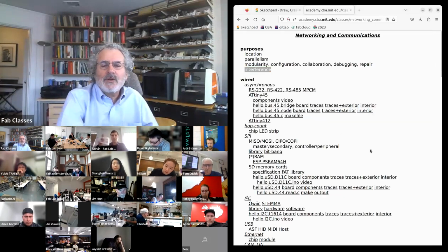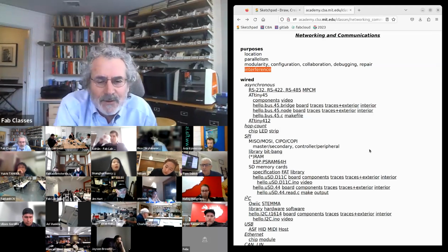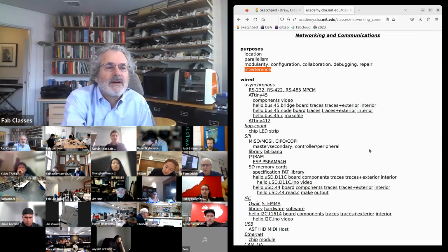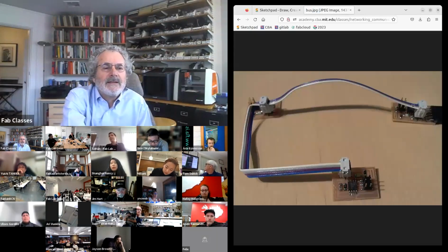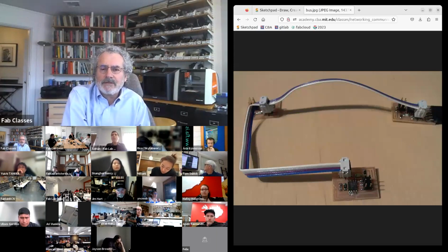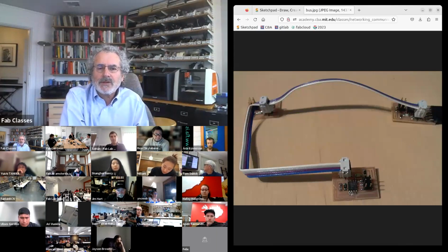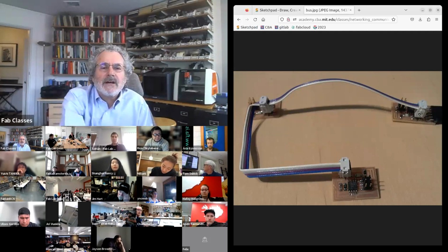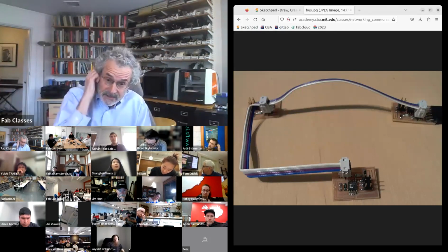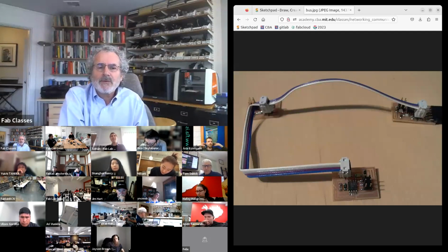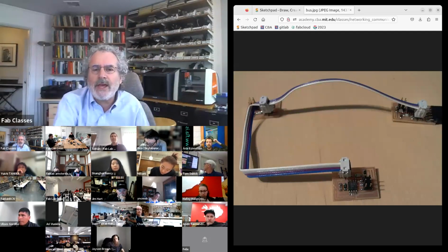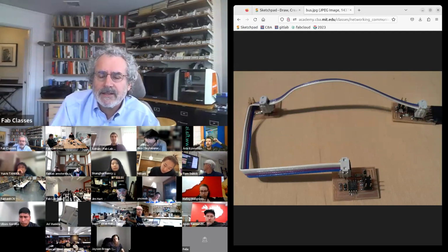So if you ignore everything else I talk about for the rest of today's class, this is all you need to do to make a bus network of processors. So this needs a host in charge, but that's usually the case. You need to assign addresses to each node and then hang them off this bus. And so this is good up to maybe, say, 10 processors. I wouldn't use it beyond that.